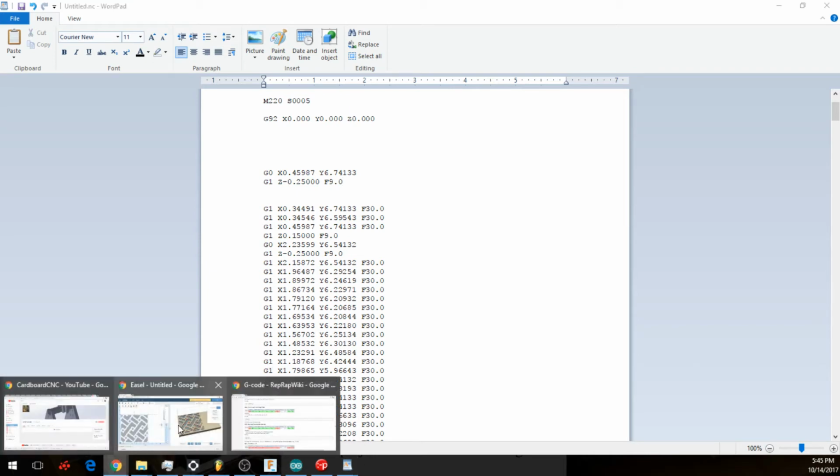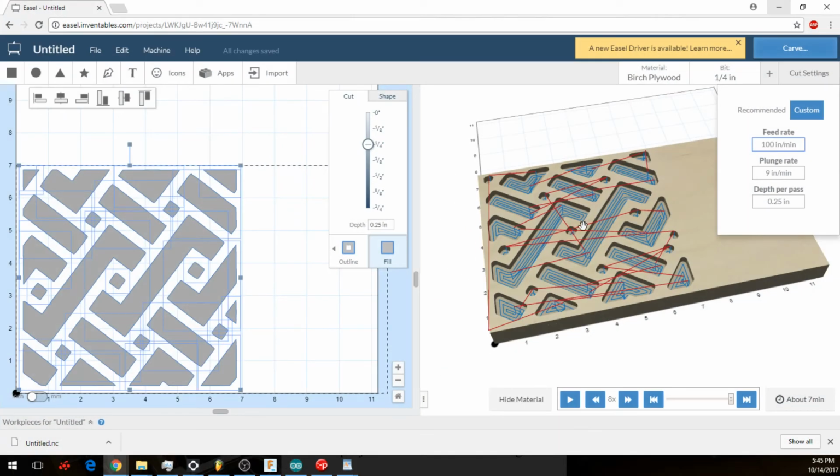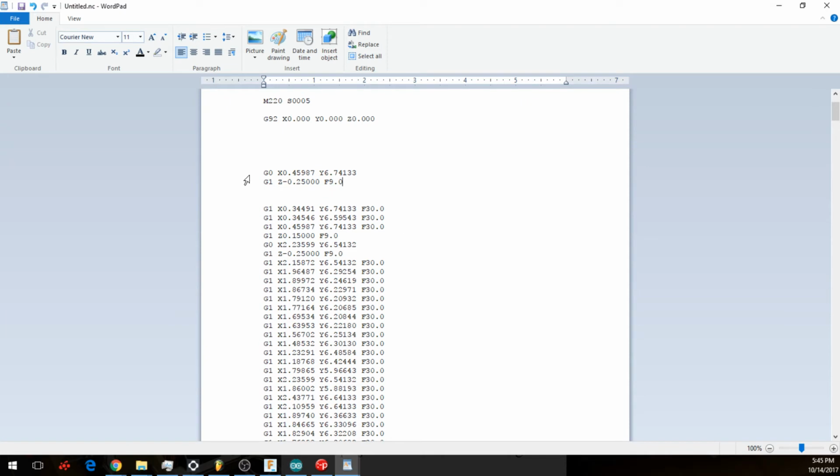And this is because if there's any variation in the height of the piece you're cutting, or you lose one step or anything small, as your head is translating from one spot to another, it'll start cutting just slightly into the top of your piece where you don't want it to cut, and we don't want that. So to give ourselves a margin of error, I use a 1/4 inch piece of MDF as a spacer, and then just always set my head to be a 1/4 inch above the highest spot of the piece I'm cutting. And so I just add that into my command.